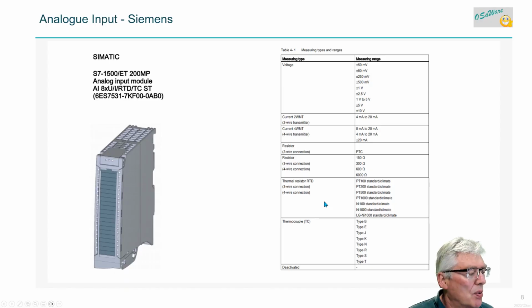So that was quick about I/O. We looked at digital I/O, sinking and sourcing, the digital output sourcing principle. We looked at digital input modules. We looked at a SICK photo detector and how, with a normally open, normally closed contact and a common, to connect that. And we looked at IO-Link a little, and just a brief picture of the IO-Link master. Siemens can use IO-Link devices, and one analog input module. And that was what this video was about.